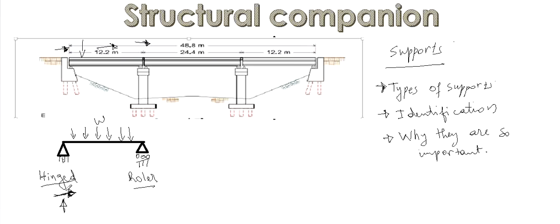Why is there a horizontal reaction? Because the hinge support cannot roll. It is fixed here, so it cannot move in the horizontal direction. There is a vertical reaction because there is no sinking, so it has to support in the vertical way and in the horizontal way. It means there is no movement at all, neither horizontally nor vertically. Now for the roller support, we have only a vertical reaction, so we will be identifying only the vertical reaction.